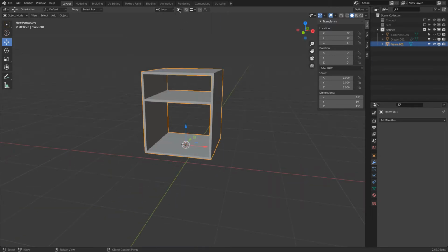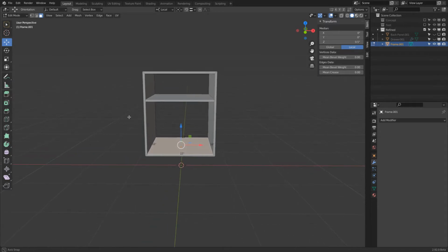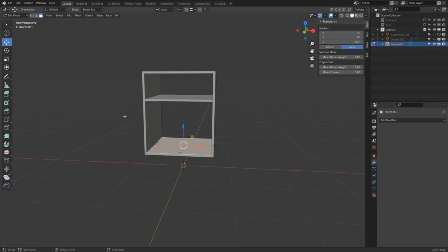we go back to bounding box, move Shift S cursor to the world origin, so everything is nicely reset. Let's go into edit mode. We will select this bottom face here. This is good.